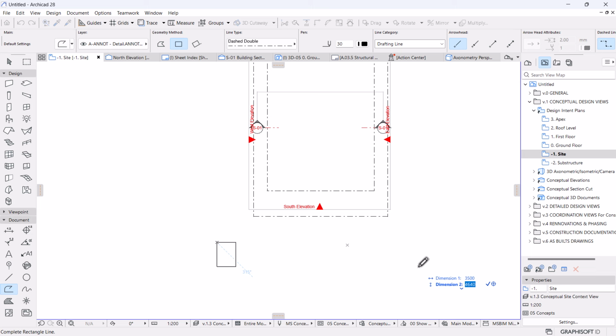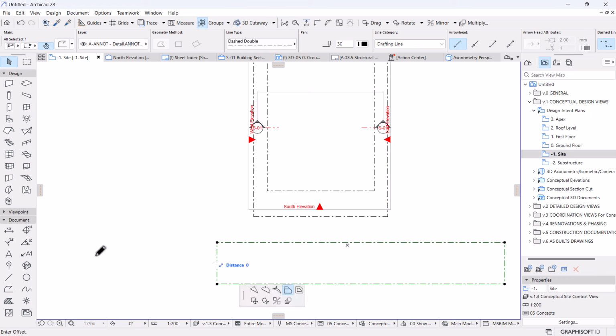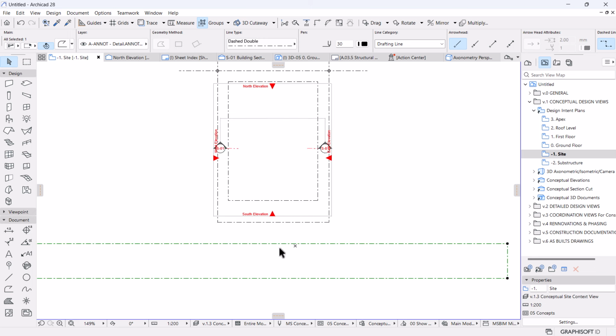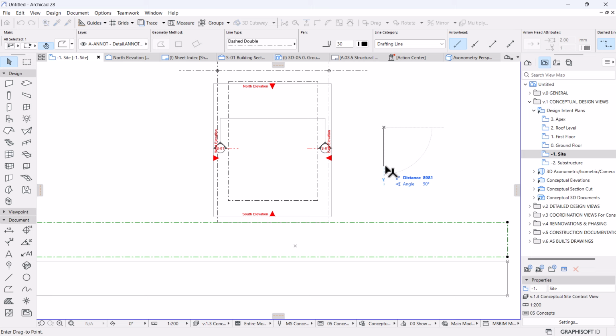In this case, it's going to be an internal road. I will assume this plot is in a real estate, where internal roads are much smaller than external roads. So I'm going to have it around, let's say, 8 meters. There we go. And then I can stretch the edge of this road to increase its length to whatever desired distance. Okay, so what I'm going to do is Control D to move this road next to the plot, and then I'm going to move it back by a value. I'm going to have it around 3 meters away from the plot.